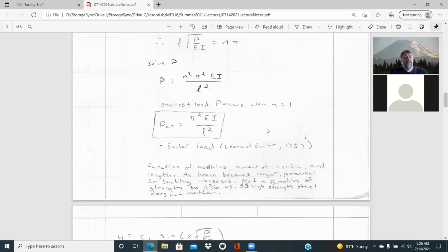And so in that scenario, you've increased the strength, but the Young's modulus is the same. So it still has the same potential for buckling as if it hadn't gone through that heat treatment. And so that's another reason buckling is really important to consider when you're looking at really loading things greatly in compression.